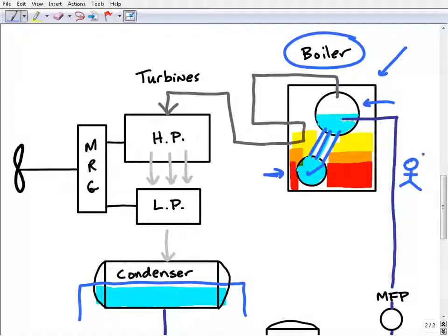Think of me as being about this size, and for you out there who've actually done this, this is really oversimplified. But just think of it, this is a big cylinder, the big water drum, that's what it's called, and these water tubes connect up here, and the water essentially fills up to another big drum, and this is called the steam drum. So if you can think of it, you filled up water and it floated down through here, filling this up. That's pretty much what we've got.